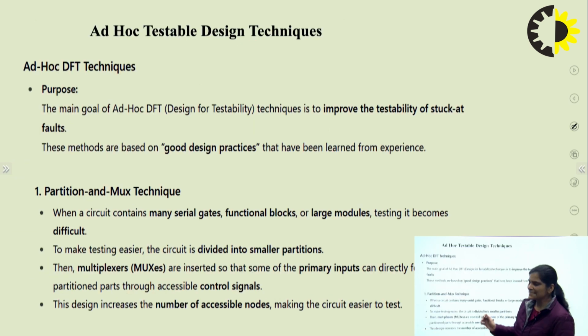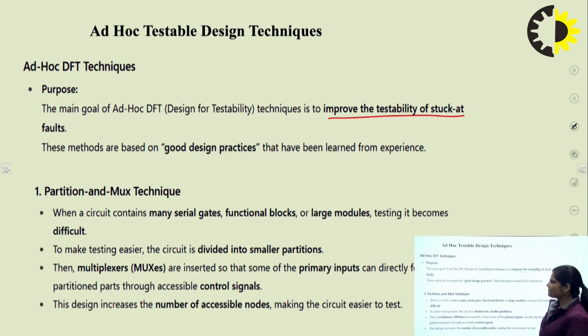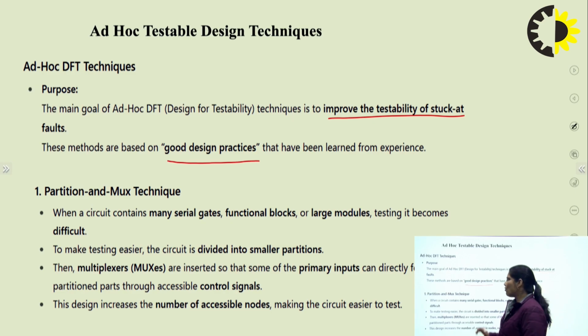Now, next is the ad hoc testing design technique. What is the purpose of this ad hoc DFT, design for testing technique? The main goal of this ad hoc DFT, design for testability technique, is to improve the testability of stuck-at faults. These methods are based on good design practices that have been learned from experience. Now, first here is the partition and mux technique.